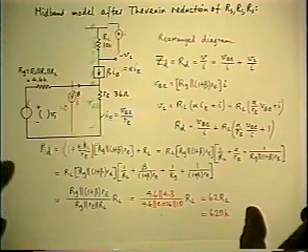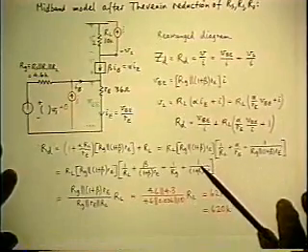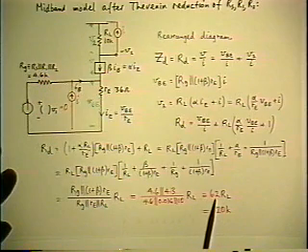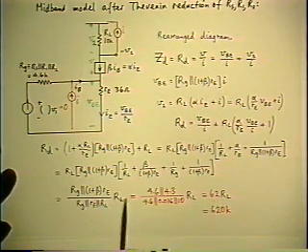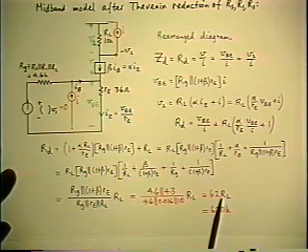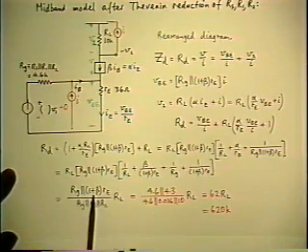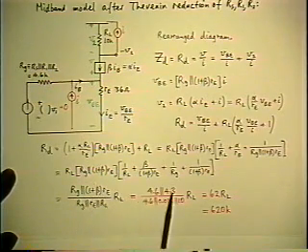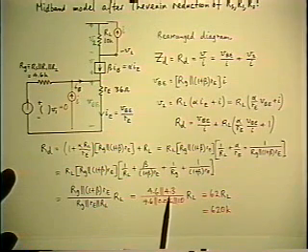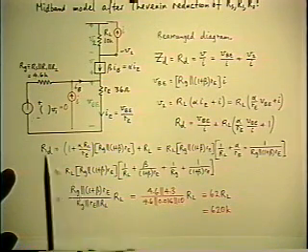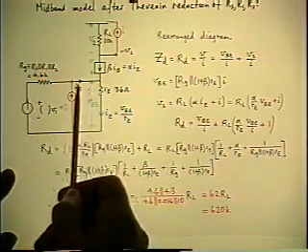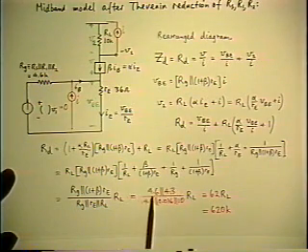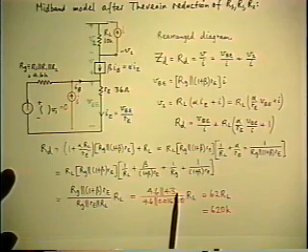Okay, so the important thing is, what does the answer tell us? Well, when you put numbers in, you see that this coefficient in front is a fairly large number, and it multiplies the RL. And look at how these numbers are derived. Again, the importance of retaining the low entropy format and plugging in the numbers in an intermediate step so you can see which ones are important. The numerator is RG parallel the reflected RE, and they happen to be numerically almost equal in this case, which means the parallel combination is about half either one of them.